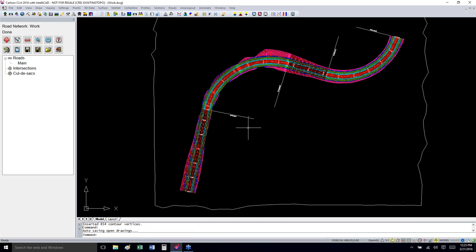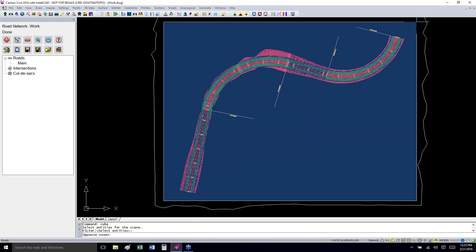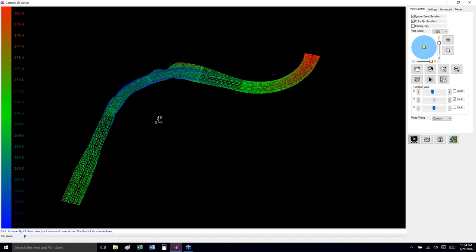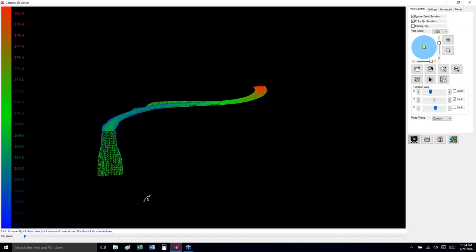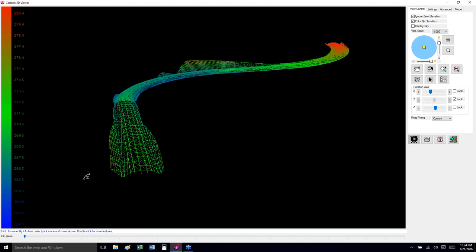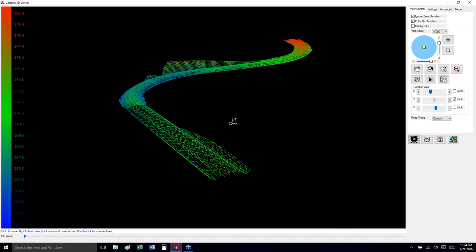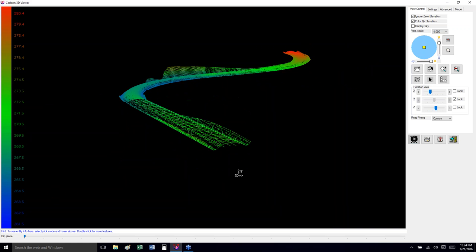Let me window up a little bit. Very colorful. Now, this is definitely one I like to go into View 3D or Window Viewer and window this roadway. I like to check all this stuff, of course, having a survey background. I'm kind of paranoid about things, so I'm going to go ahead and exaggerate this as well so we can see some relief. And let's window in and look at our road. Now you can even see as I tilt it down, as I get the Z, we can spin. I come up in the screen, I get the X, Y, and I can tilt.